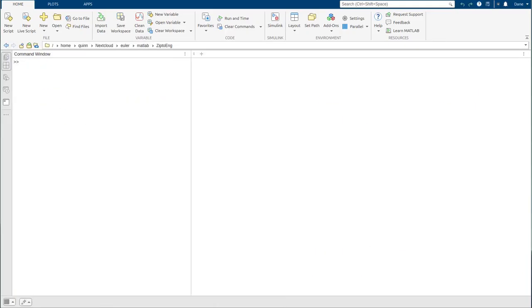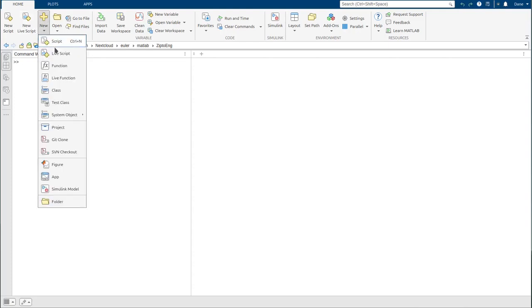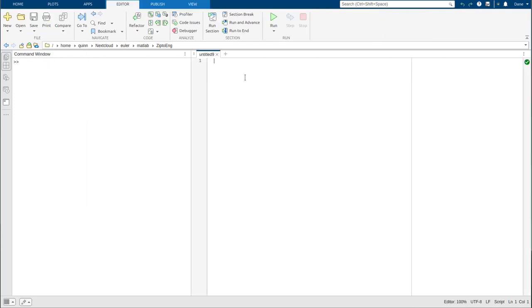Here I have my MATLAB command window. The first thing we need to do is obviously define that derivative function. So let's open up a file here, and we'll type in what we saw on the previous screen. Function, this tells MATLAB that we're defining a function. X dot is equal to deriv first order, as a function of t and x.